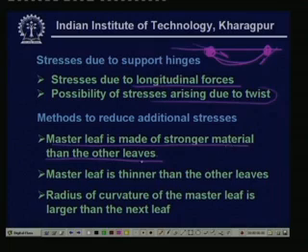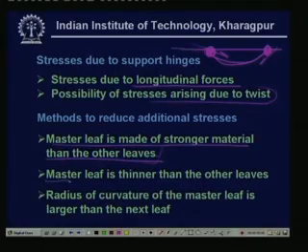That means if you make it of a stronger material, then obviously it will be able to take up more stress. Another way is that you make the master leaf thinner than the other leaves.